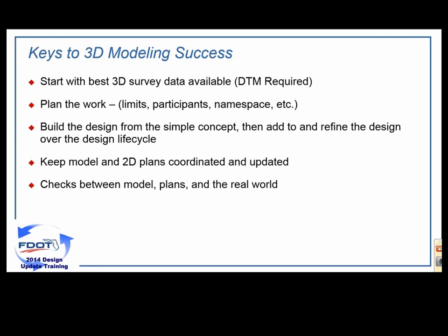You also want to plan the work. What we mean when we say that is, before you get started, you want to sit down and think about it. What are the limits of the job? Do you have a huge DTM? If so, you might want to break it up into smaller, more manageable sections, depending on your hardware. What are the participants? Are you going to have just one person doing this modeling, or are you going to have a crew of people, 3 or 4, working on it? If that's the case, then you're going to need to also break it up because, as you probably know, Windows will only let one user at a time access a file.